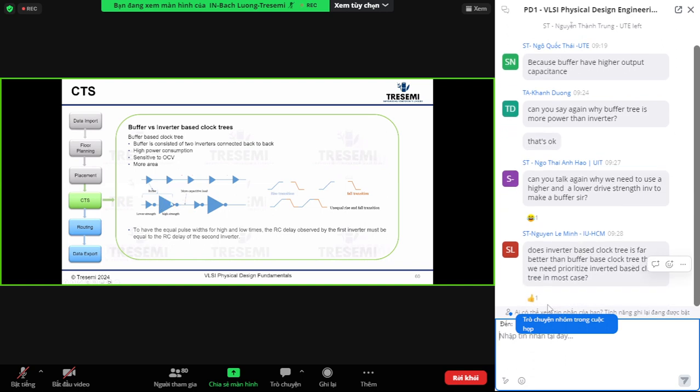But here we need a larger buffer because this is the outside world. You could have a long net, which is a higher loading, right? It's your C load, your capacitance and so on. So that's why we need a bigger buffer here. But this is internal to the buffer that you use. It's not something that you need to build.